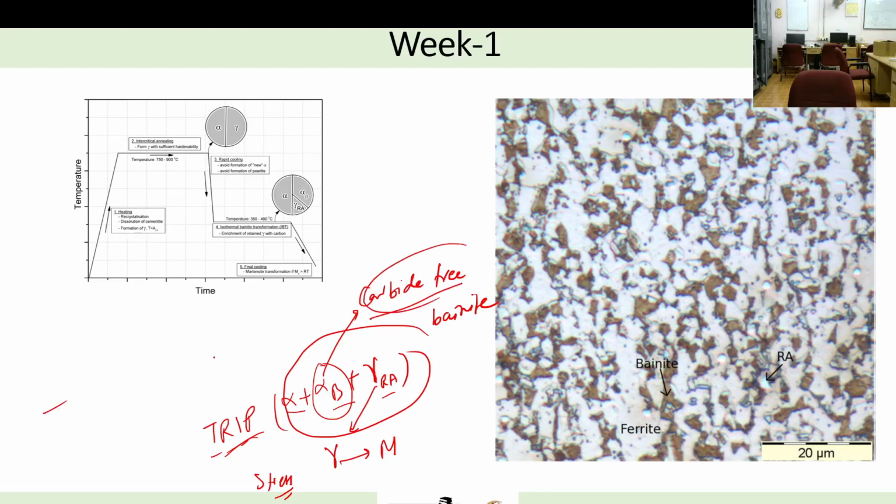So in this bainite, it will be only a ferritic matrix. No carbide will be formed, and this ferrite matrix will be enriched in carbon. So these are nothing but carbon supersaturated ferritic matrix. So we call it a bainite, which is nothing but supersaturated ferrite. That's why I showed it with the alpha. Alpha is the symbol of ferrite and a kind of bainite.